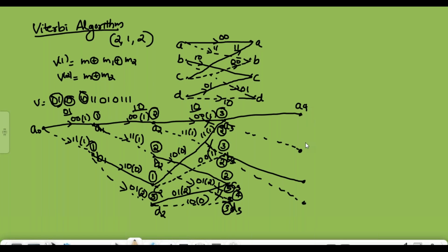Then here 3 and 2, therefore the higher metric is 3. Put a cross mark on that particular path. Here 2 and 5, avoiding the 5, so remove that one. Then here 4 and 3, therefore we put a cross mark on the path which is being removed. We continue with the other branch and maintain the paths from this.